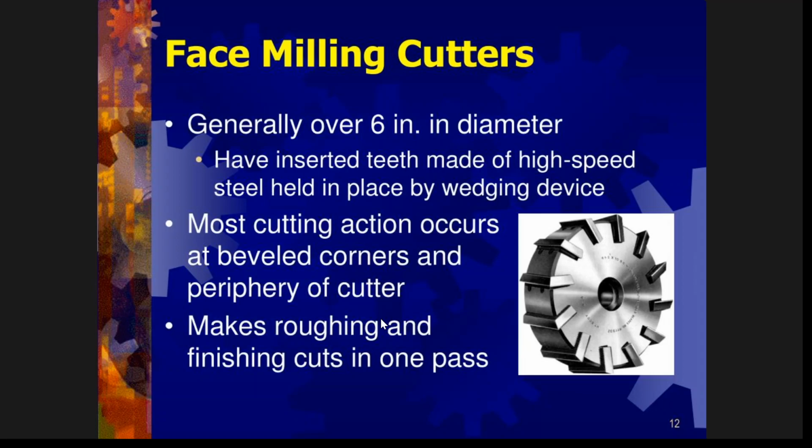And the face milling cutter is widely used in vertical milling machines. That is very important. This is used in the vertical milling machine for machining flat surfaces and for machining pockets. Here you can see the cutting edges are on the face as well as on the periphery. Both are there. This is in the vertical milling machine where the spindle is vertical, and this surface is at the bottom of the spindle. At the bottom of the spindle, this surface will come, and this is the surface which touches the workpiece.